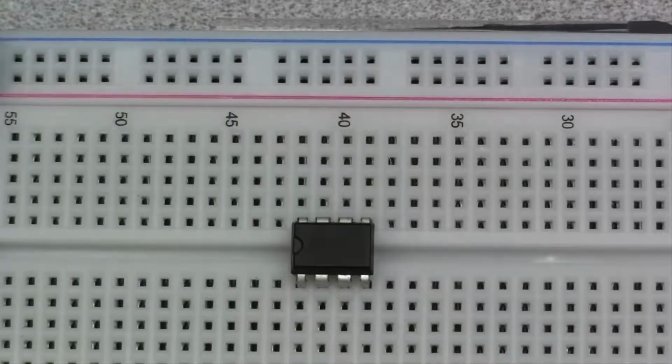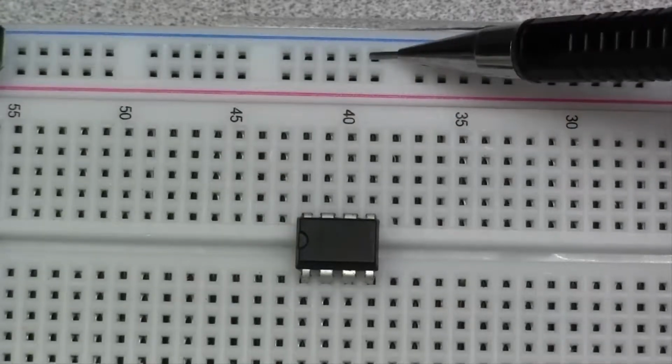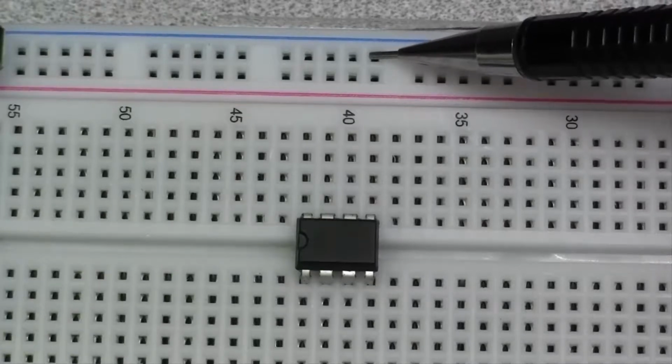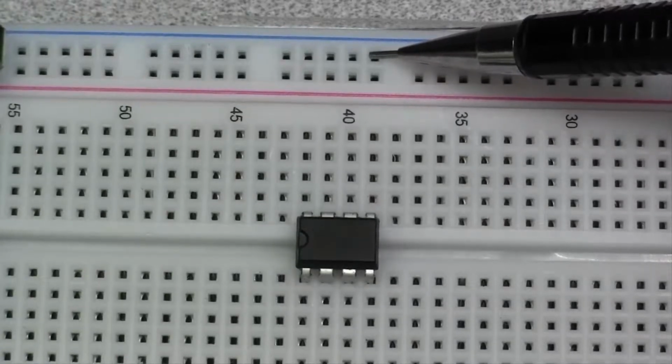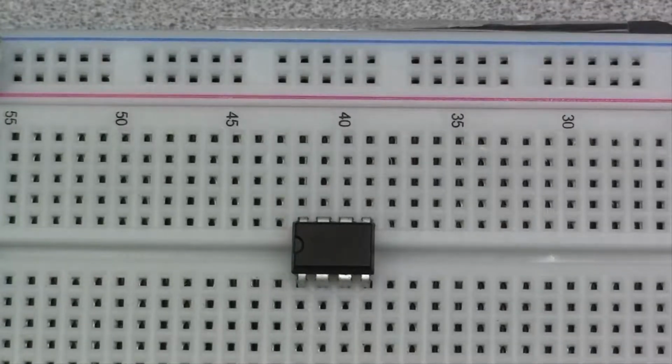We'll always need to provide power to the circuit, so I'll go ahead and connect the voltage supplies now before we wire up the rest of the circuit. By default, on the Rex Qualis power supply, the breadboard holes with the blue stripe are the reference voltage. So I set up the power supplies relative to those voltages so the power supplies share the same reference as the input voltages. I'll use 9-volt batteries as the power supplies.